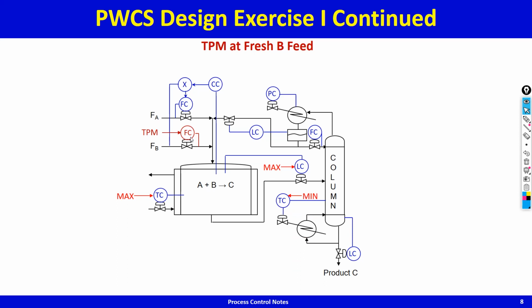The temperature controller should have the least possible set point, so that the purity of the product is at the quality guarantee that you're giving. So if the quality guarantee is 99 mole % pure product, then the purity of the product should be exactly 99 mole %, not 99.5, because then you're selling 0.5% product for free.